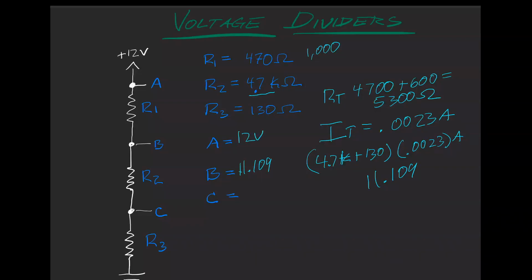You'll see that as this resistance has decreased, this voltage has decreased also, and then of course correspondingly C is going to go up. That's not really too important, but remember, this is like a transistor starting to turn on. I've got a little more current flowing up through here. My voltage has decreased at B as the resistance of R2 has decreased.